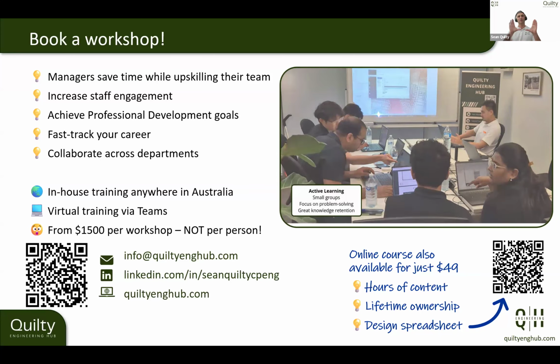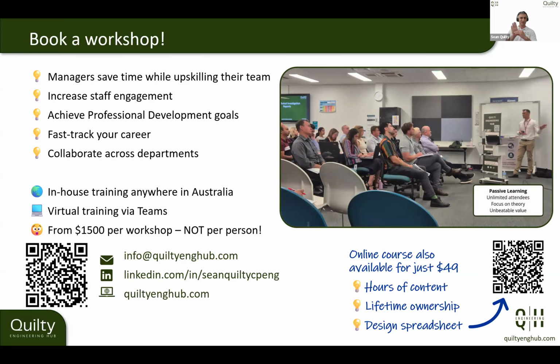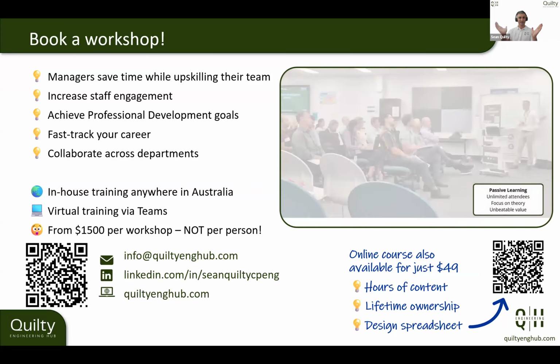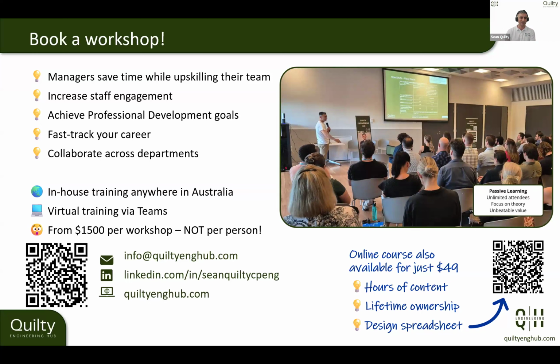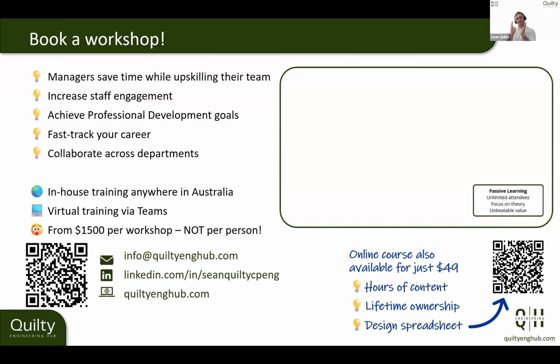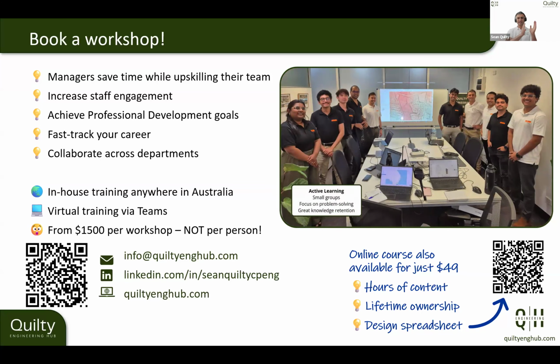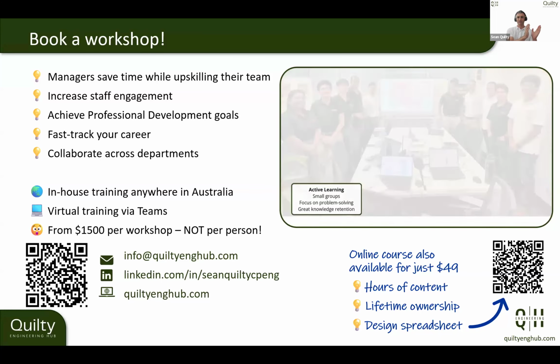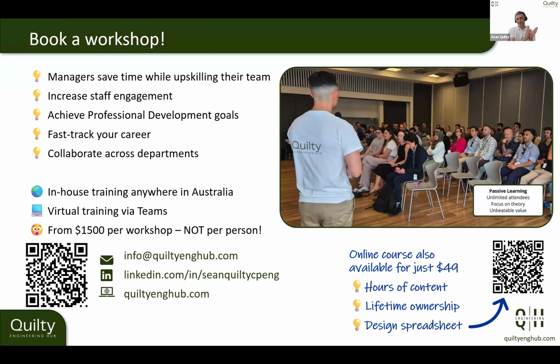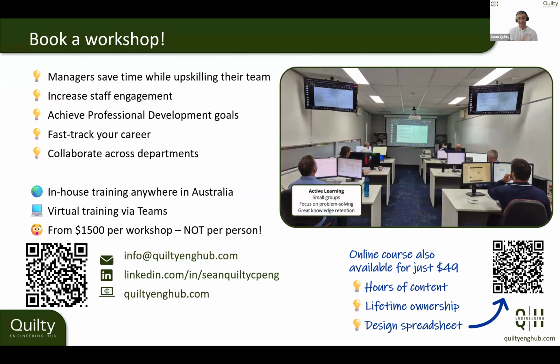If you're talking about the one section and it changes, so you've got concrete at the bottom and maybe grass on the sides, that's where we would start to look at what we call a composite section. And we basically start cutting that drain section into pieces. Then we would look at individual Manning's calcs for, say, the batter with your grass, different Manning's value, different wetted perimeter, different area. And then you have the concrete, and then you have the grass on the other side. And you basically just add them up.